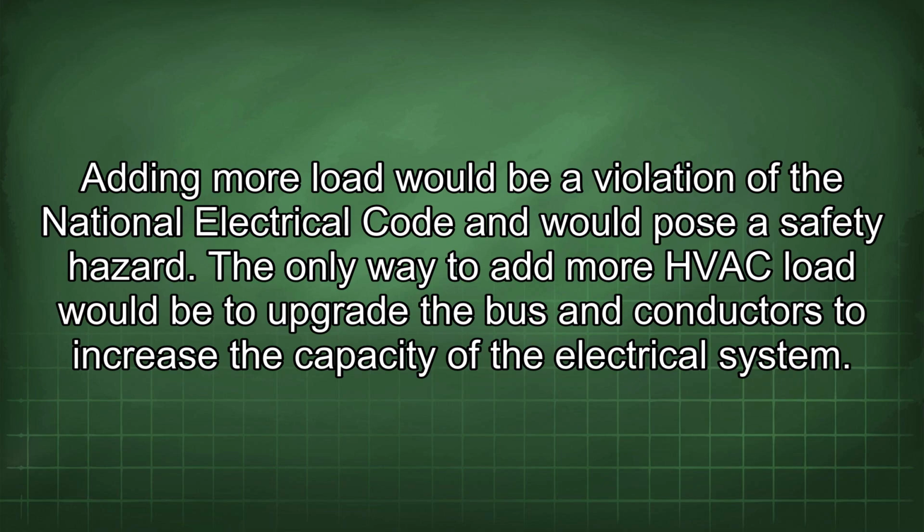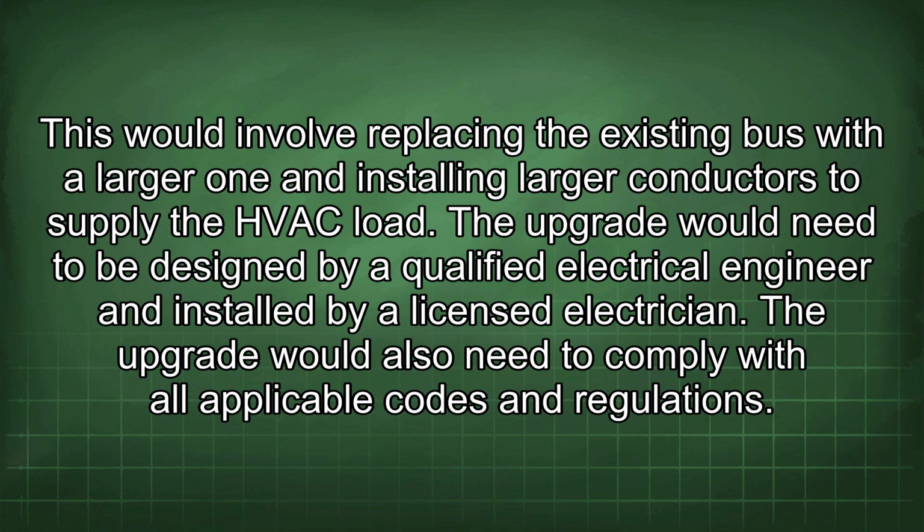The only way to add more HVAC load would be to upgrade the bus and conductors to increase the capacity of the electrical system. This would involve replacing the existing bus with a larger one and installing larger conductors to supply the HVAC load. The upgrade would need to be designed by a qualified electrical engineer and installed by a licensed electrician. The upgrade would also need to comply with all applicable codes and regulations.